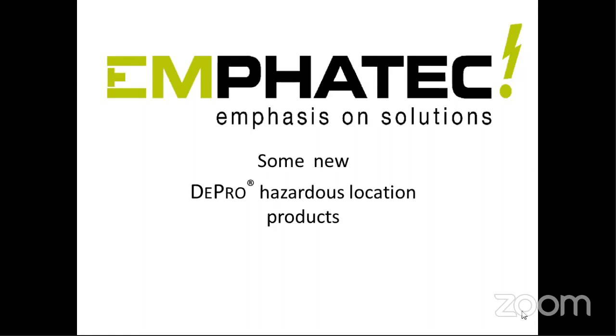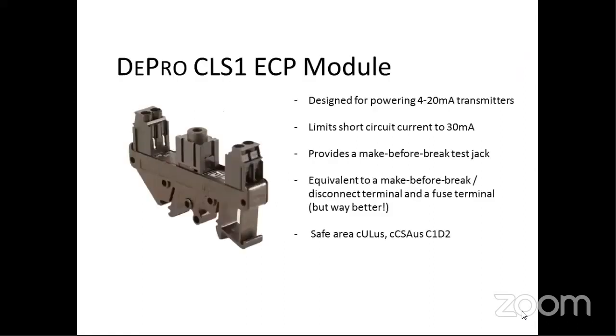Sorry about that. Just to show you a couple products that we have for overcurrent protection. This is the one I touched on earlier for 4 to 20 milliamp loops. It would sit between the power supply and the field wiring going out to the transmitter. So this would take 24 volts from the power supply through this device, runs the transmitter, the analog signal goes back to the PLC. If you get a short circuit in that wiring, this device will clamp the current at 30 milliamps. So the power supply will never get a chance to switch off.